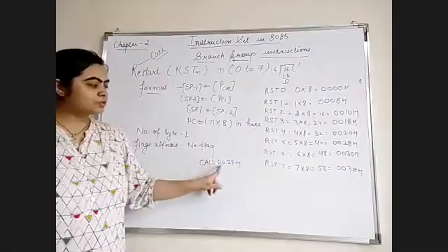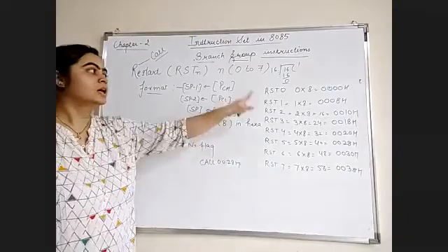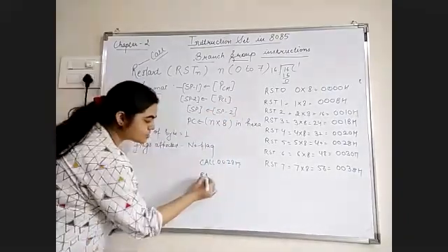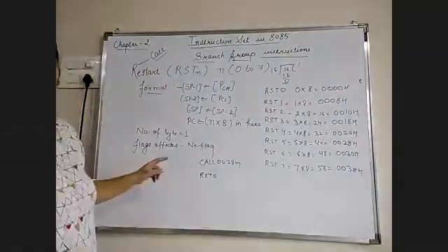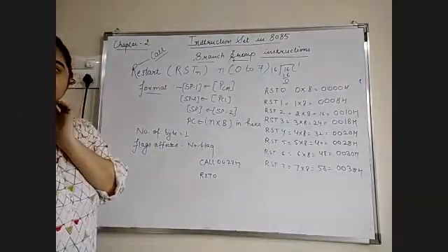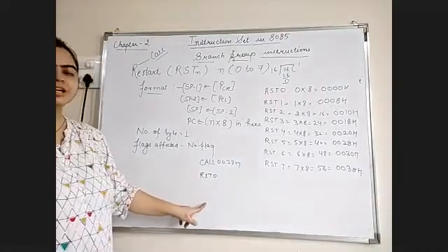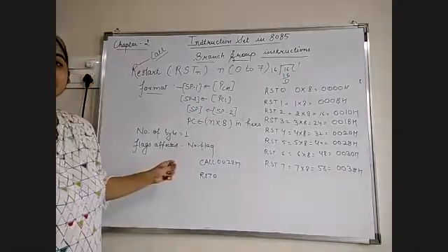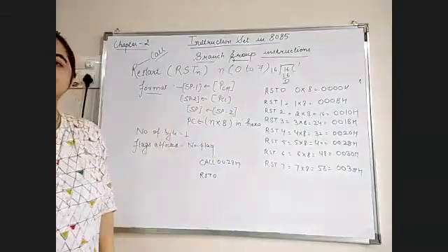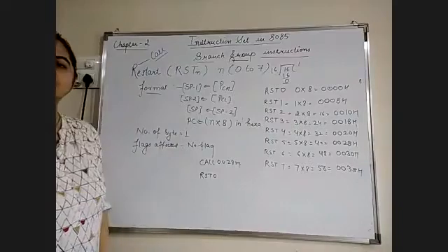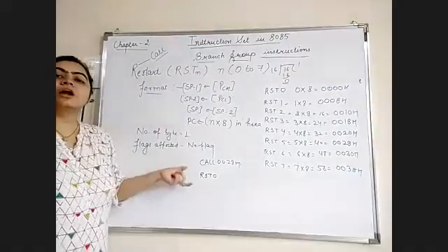Okay, after this the program counter is updated with 0028H. In the call statement we are doing like this. Similarly, in case of RST0, the microprocessor pushes the contents of the memory location which is after this instruction into the stack memory, and after pushing the contents it will jump to the memory location which is specified by calculating the vector address. So it will go to the memory location 0000H, and the program counter is updated with this address. So that means call and restart statements are doing the same functionality.